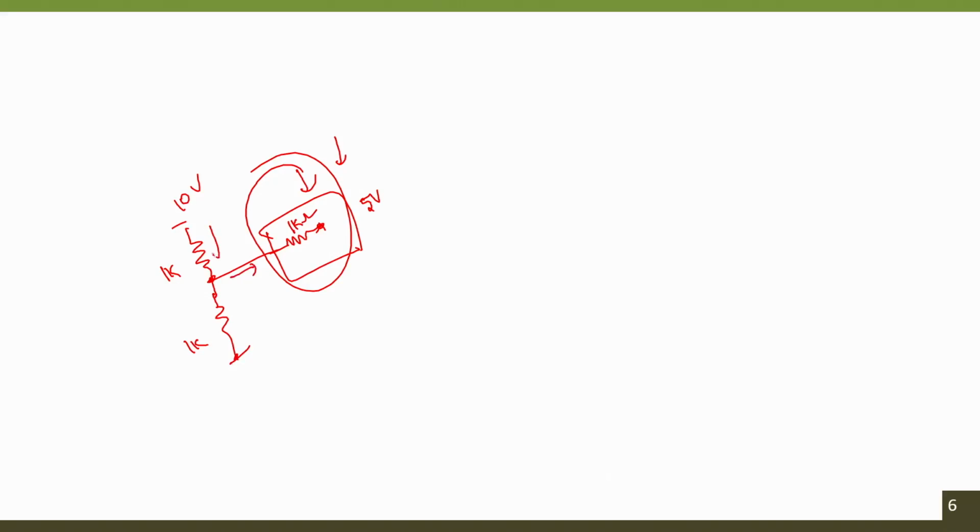So, whatever current you are getting will not change, neither the input current nor the output current, because of connecting a simple external circuitry. That is very important when we are designing a signal conditioning circuit. There should not be any mismatch or current drawn, or power consumed from the input source. As a result, if there is consumption of power from the input, be it in terms of voltage or current, the information of the input will be lost when you are transmitting to the next stage. So, this is nothing but your loading effect.